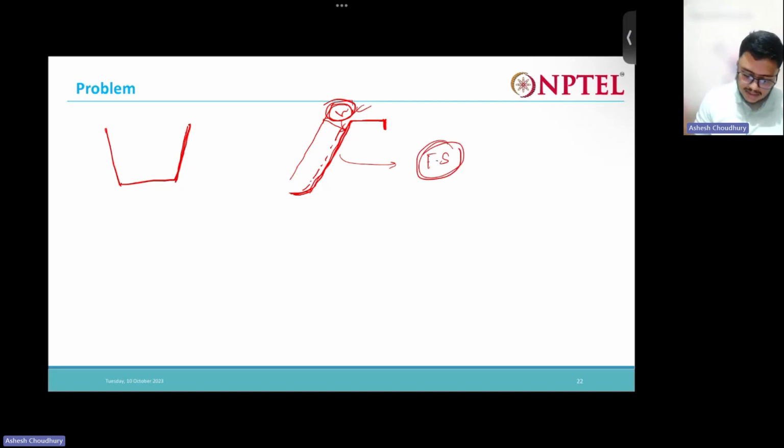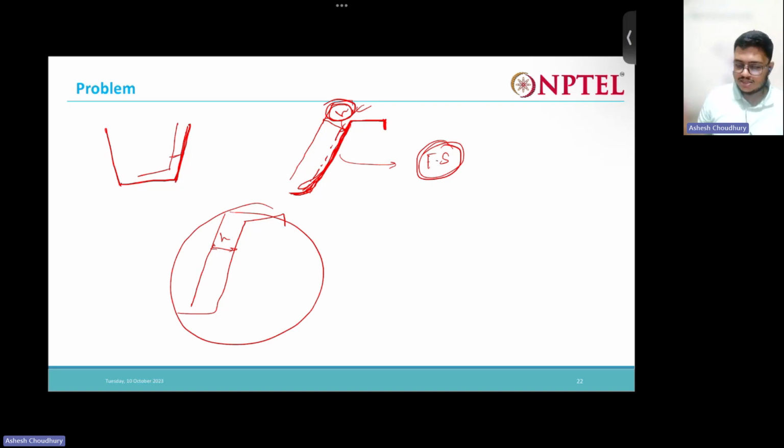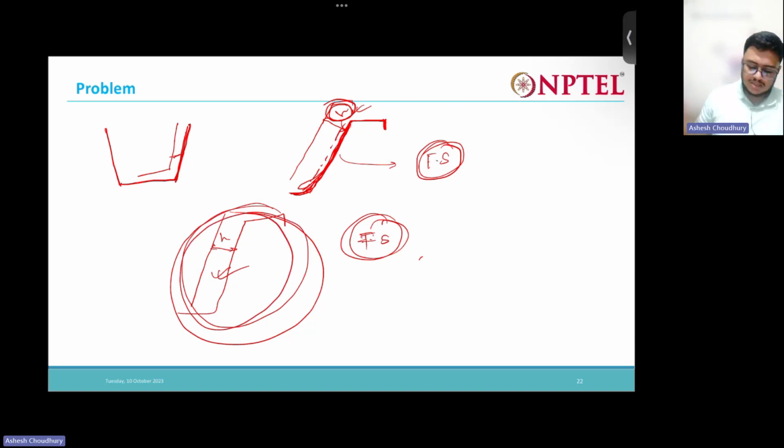Factor of safety for this whole arrangement that you are doing. You are placing the geotextile, and over that you are putting soil of thickness H. Whatever arrangement you are doing here to construct your landfill, you have to ensure that this is stable, right? So you will find out the factor of safety for this, and we'll see how to find it, so that this condition is stable.